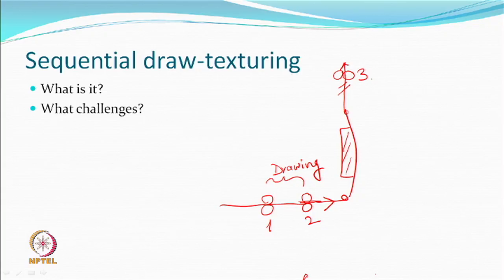If it was nylon, it goes like this, or if it was polyester, one could put a hot pin over which the yarn is moving. So, the temperature of the yarn could be raised, and then you can do the drawing. So, this was all done, a simple extension, and a machine could actually get to sequential draw texturing.